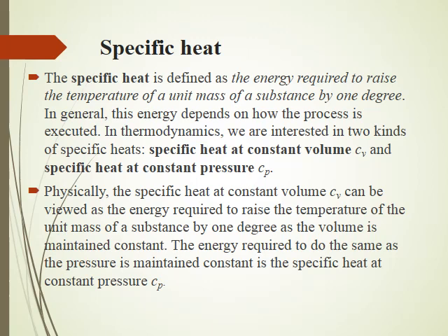But even we can think logically about why Cp is greater than Cv. Because at constant pressure the system is allowed to expand, and the energy for this expansion must also be supplied to the system. That is why Cp is greater than Cv.